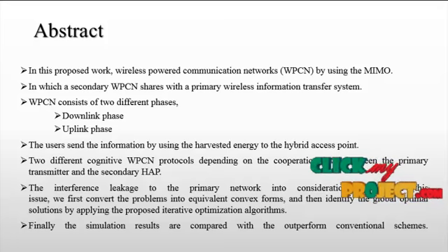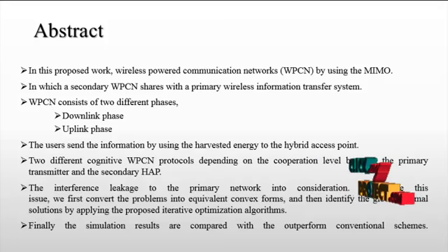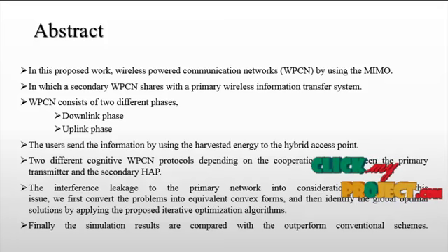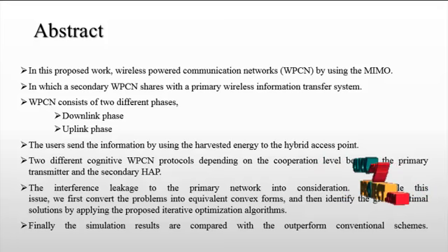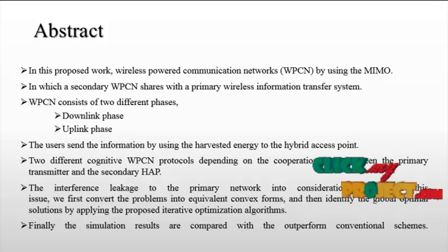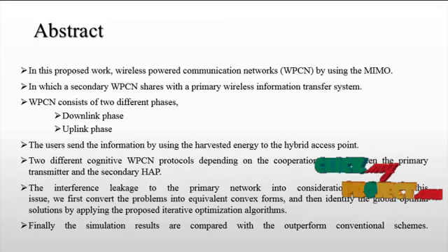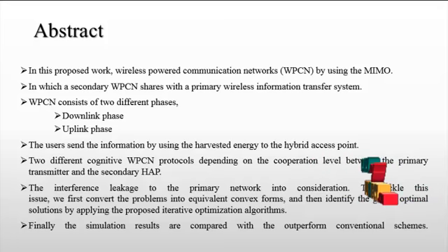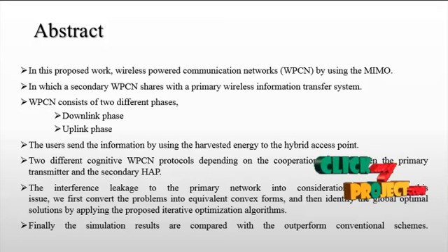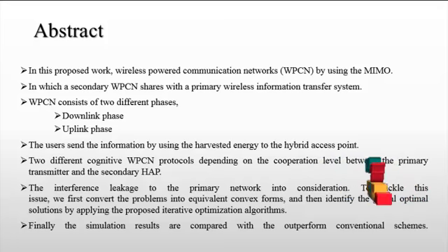The multiple antennas in MIMO systems can be exploited in two different ways. One is the creation of a highly effective antenna diversity system, and the other is the use of multiple antennas for the transmission of several parallel data streams to increase the capacity of a system. Antenna diversity is used in wireless systems to combat the effects of fading if multiple independent copies of the same signal are available. They are combined into a total signal of high quality even if some of the copies exhibit low quality.